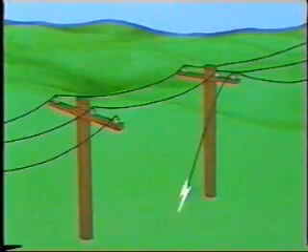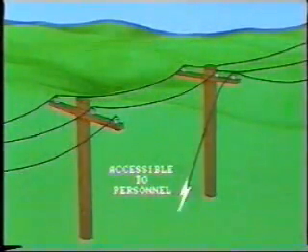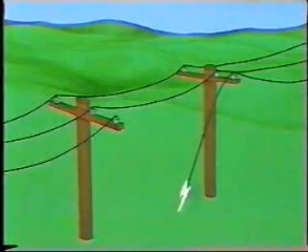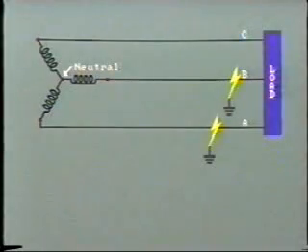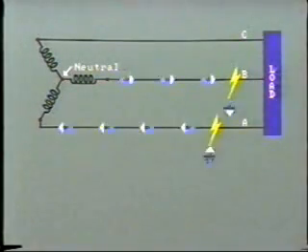First, at the fault location, we have a live conductor coming into contact with ground, which may be accessible to personnel. Moreover, there may be an arc present, which if not interrupted will cause serious damage by burning. Another problem becomes evident if a second ground occurs at another point in the system, say on another phase. In this case, we have effectively a short circuit between the two phases, and this could cause a serious upset to the system. For all of these reasons that we have just explained, ungrounded systems are rarely used.